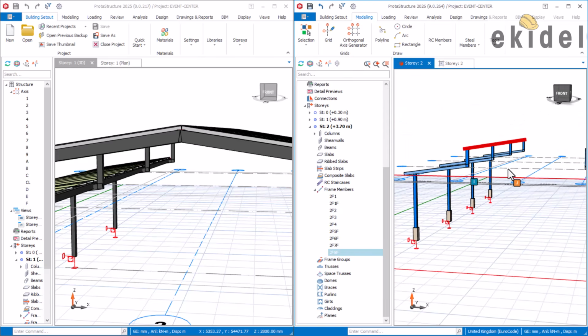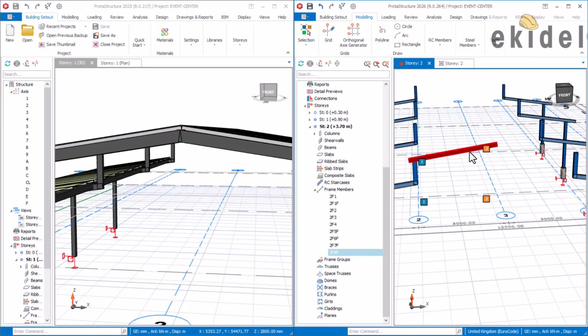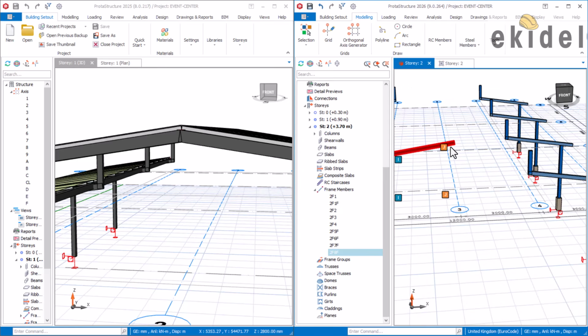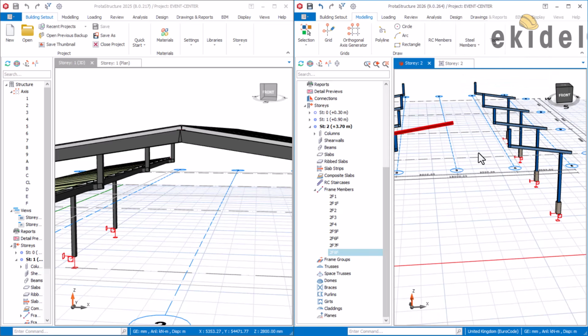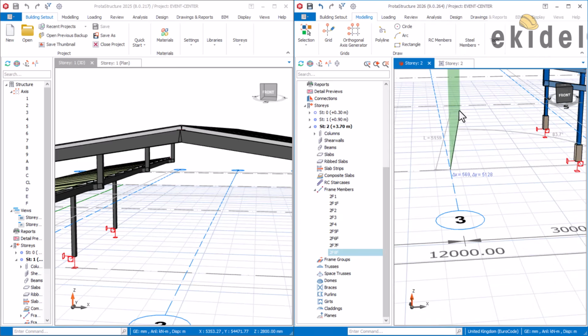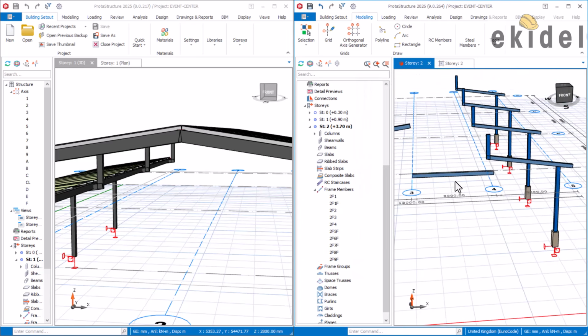Now there is something I did. This vertical, okay, hold on first. So we are now going to mirror this to be on this one. Click here, right click here, and then say mirror. On that mirror option, we will click at this point where it meets, and again here where it meets, and then say okay, that is fine. So we are going to have this here.